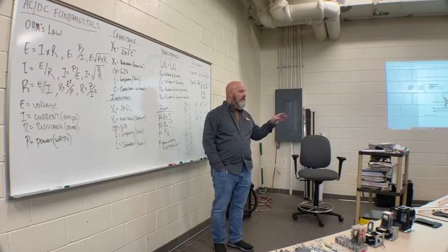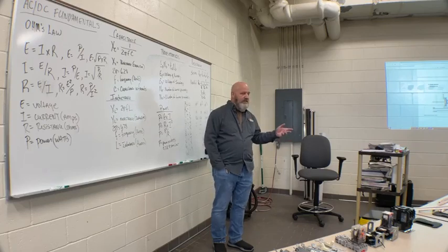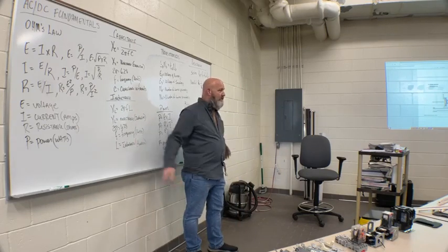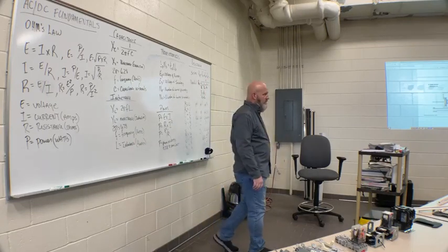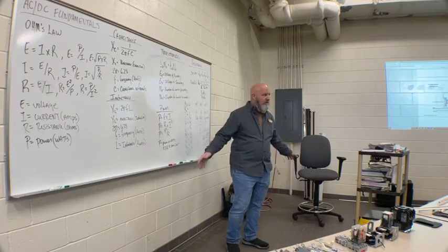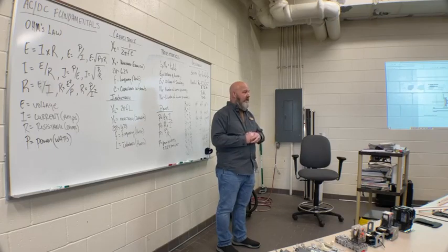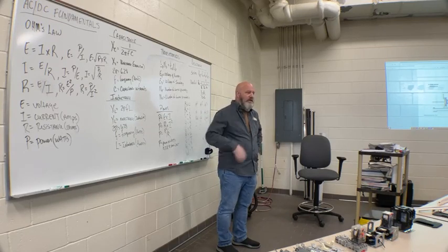See what I'm saying? The code also says, which I'll tell you this, in a residential dwelling, your receptacles are 12 feet apart maximum. Your receptacles can only be 12 feet apart in a residence on the wall. That's the maximum they can be. But the code says any place along the line of the wall cannot be more than 6 feet from a receptacle. And then students go, what?